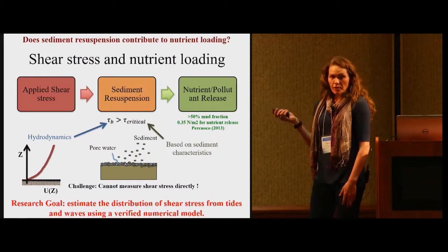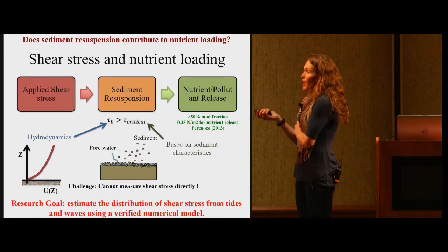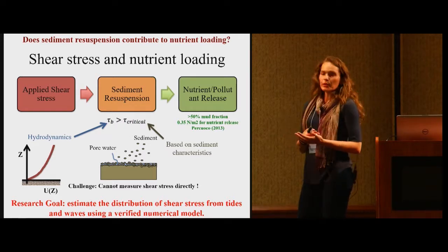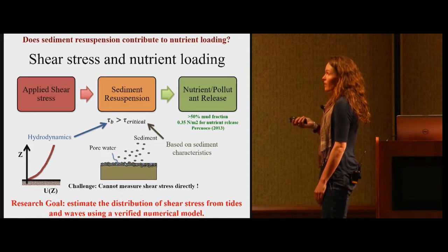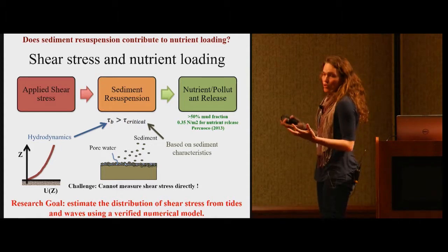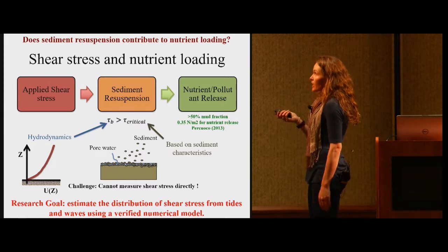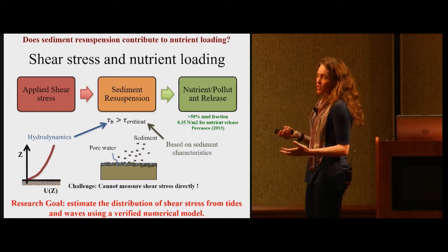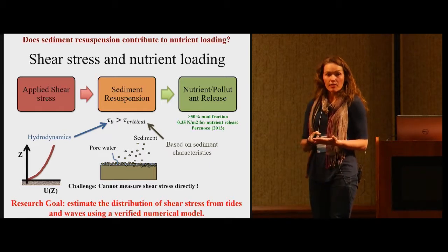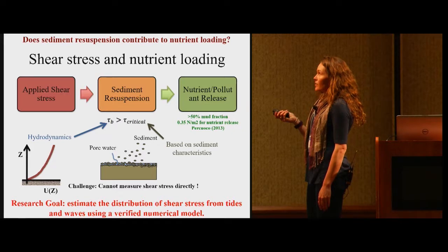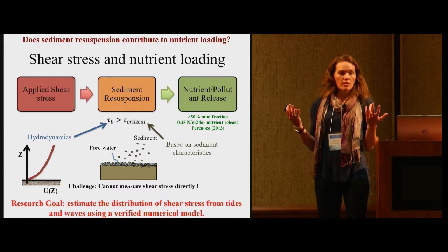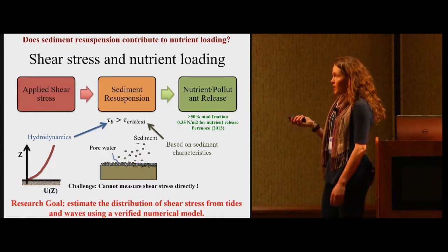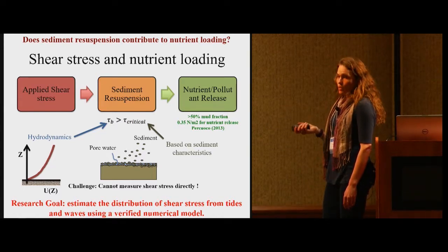This is how shear stress relates to that nutrient loading. When you have a fluid interacting with a boundary, it applies a shear stress at that boundary. In our case, our fluid is just the motions of the hydrodynamics over our system, and that induces a bed shear stress. When it exceeds some critical threshold, which is set by the sediment characteristics, the characteristics of the bed, you have some sediment resuspension, and depending on your environment, you can then release nutrients into the water column. Those nutrients either can be within the pore waters or attached to the sediments themselves.